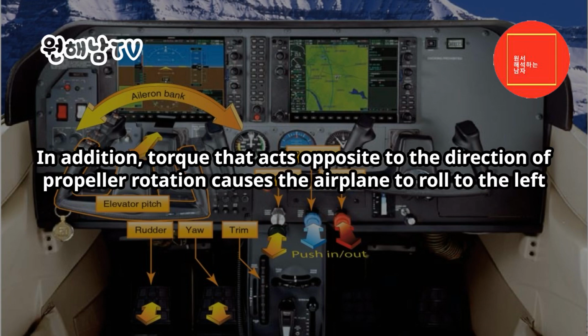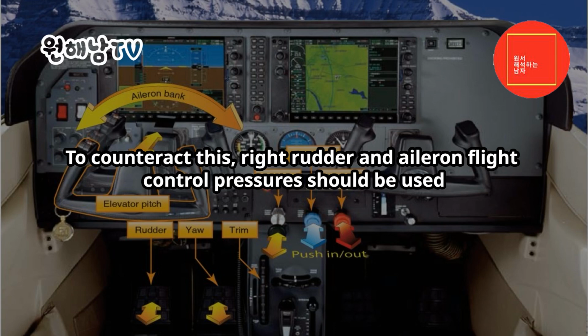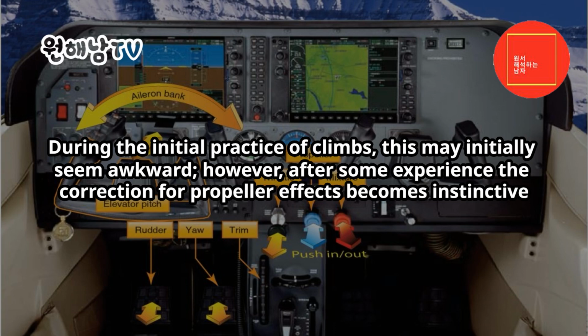In addition, torque that acts opposite to the direction of propeller rotation causes the airplane to roll to the left. Under these conditions, torque and P factor cause the airplane to roll and yaw to the left. To counteract this, right rudder and aileron flight control pressures should be used. During the initial practice of climbs, this may seem awkward. However, after some experience, the correction for propeller effects becomes instinctive.